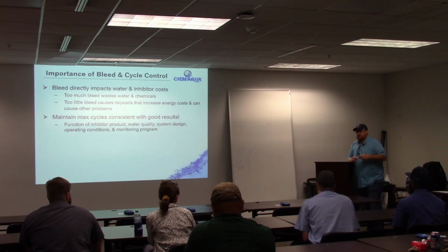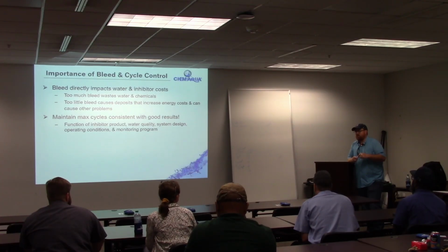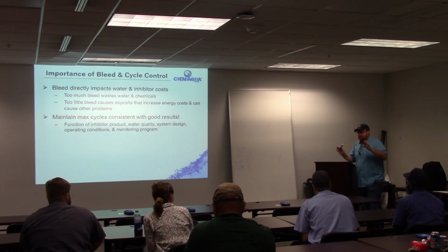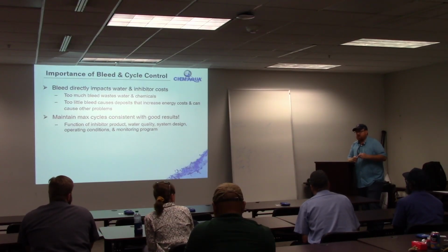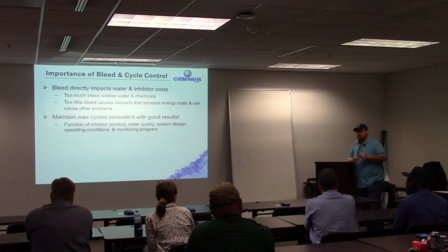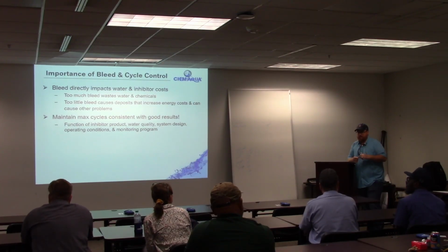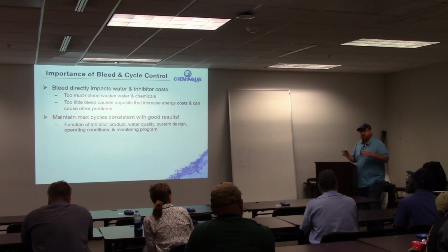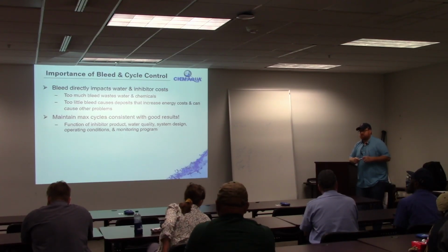At the very end of the line, in New Orleans, sitting in Kenner. Yeah. So the city water's pretty standard across the board. Right now it's around 520 conductivity, total hardness is around 190, pH is about 9, alkalinity is about 100, 110. It's pretty standard across the board. So your location within the city isn't going to have too much of an impact.